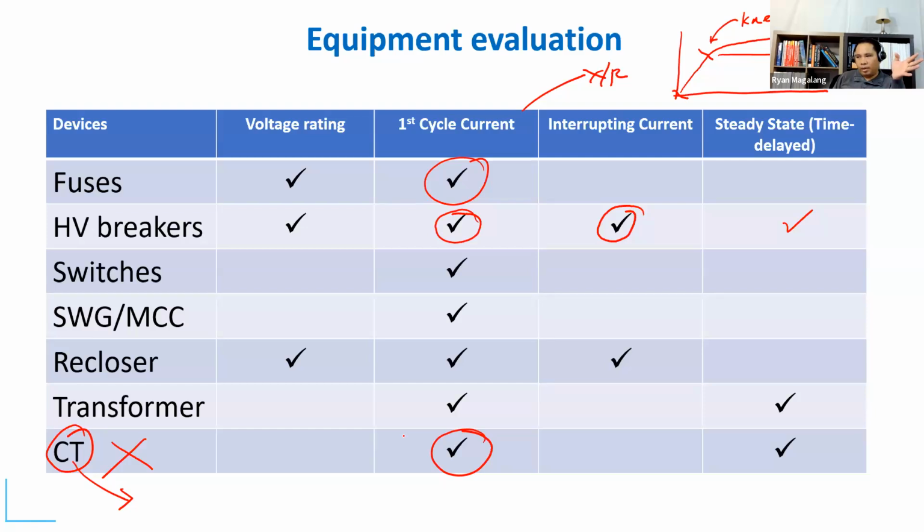So maybe you could estimate that for a mall or an office, 30% motor, or maybe less than 30%. But try to look at the panel schedule, the load schedule, and you could approximate. And you're only interested in the motors because that's the only one contributing to the fault current.